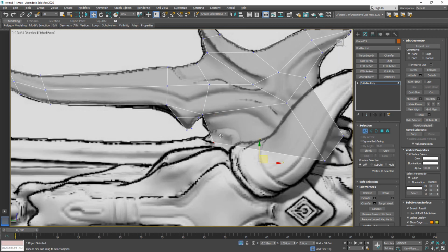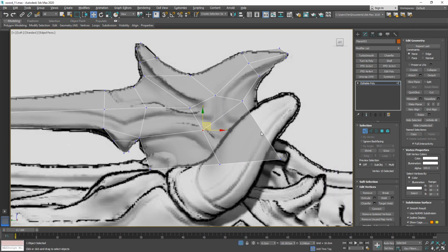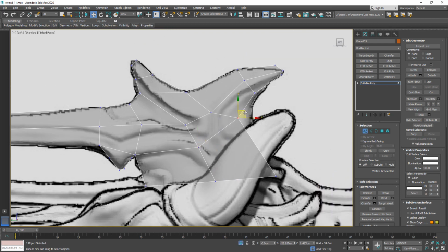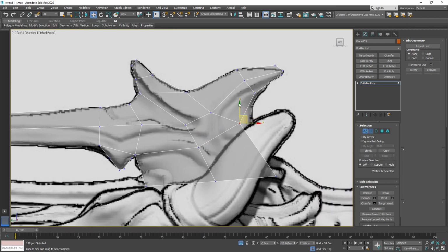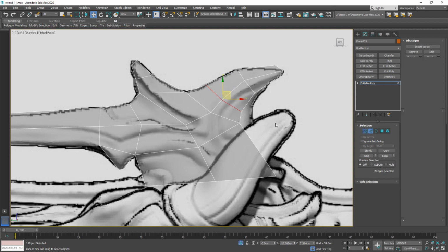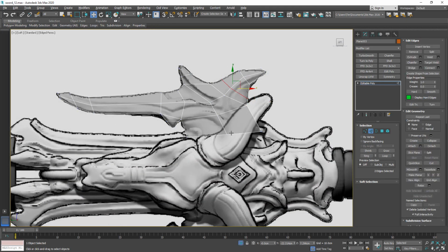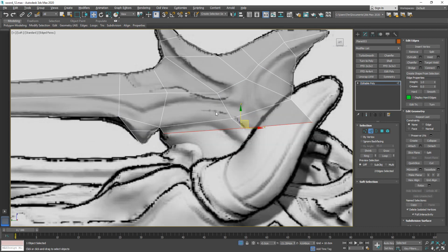So it's really hard to comment on every single step here. But let's just look at what we have there in the background and put these vertex points and edges where they make sense and have a connection here also, so that we have a bit more of a curvature there. And let's take these two edges a bit more back up here.